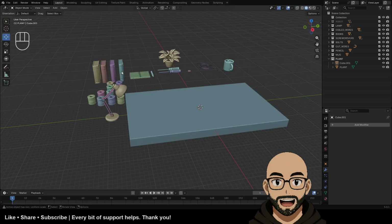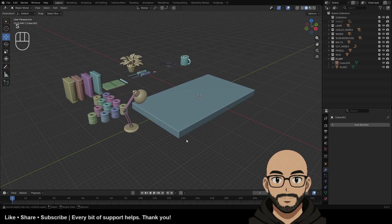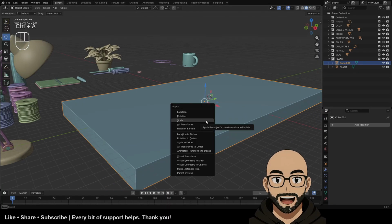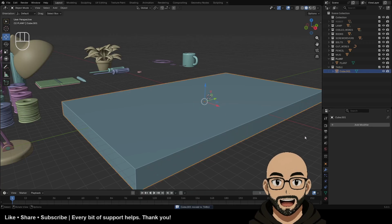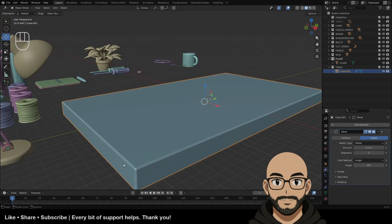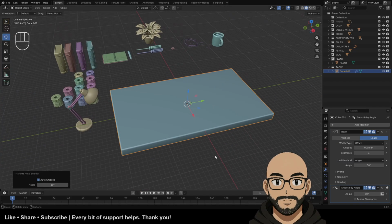Now already looking at the proportions of the table against the objects, maybe the table can be a little bit smaller. Alright. I'm going to hit Control A on this scale. I'm going to put this in the new collection. I will just call this table. And I'll add a bevel on here. I don't want these hard edges. Alright. Shade auto smooth.